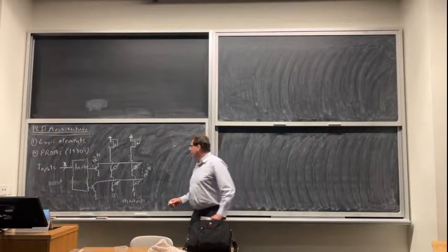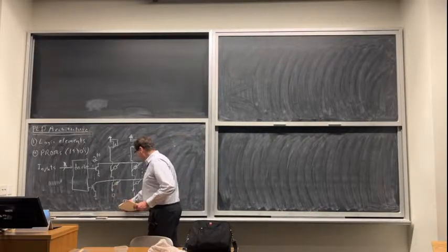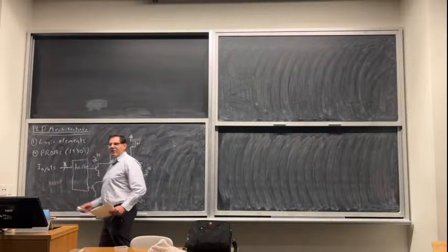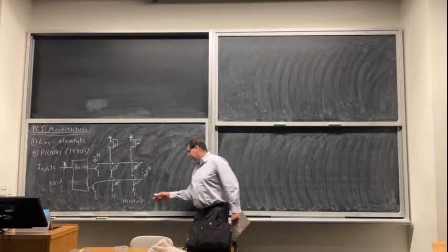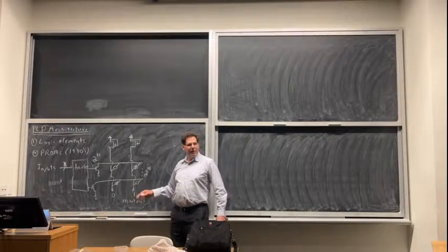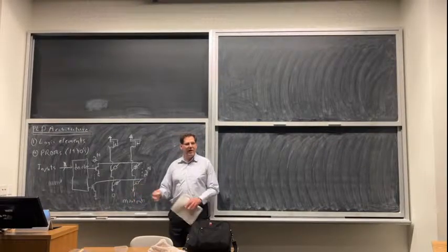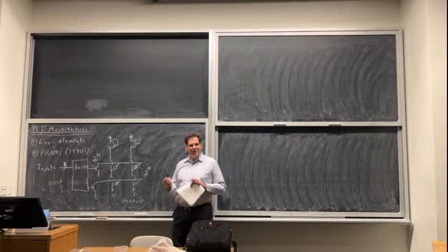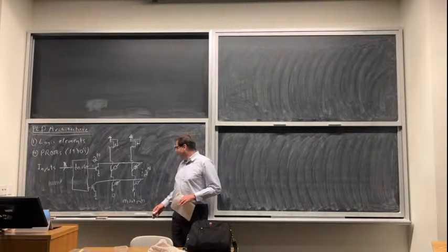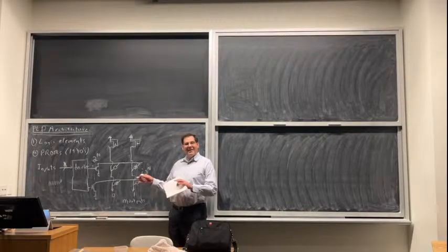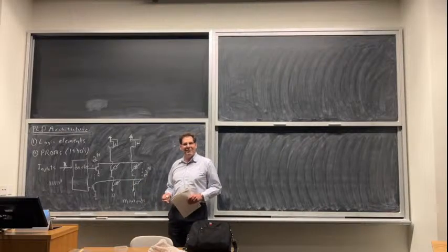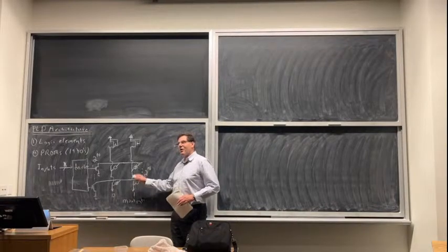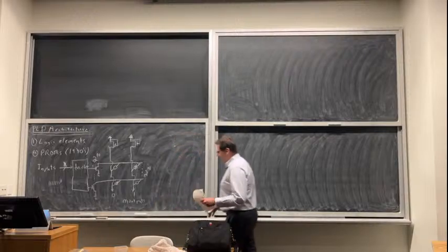So that means if I have m outputs and n inputs, I can do any function of my n inputs. And actually not just one function, I can do m functions because I have m outputs of my n inputs. Does that make sense? And hopefully you get the circuitry. I confused myself as I was doing this, but now I have notes. So I've recaptured which is a 1 and a 0, hopefully with me.